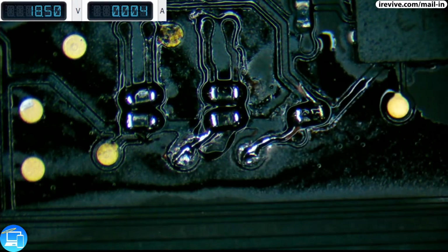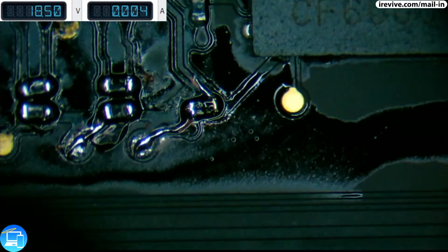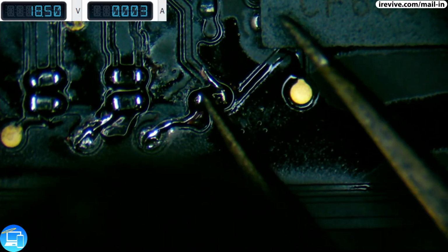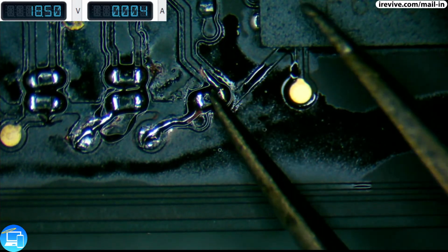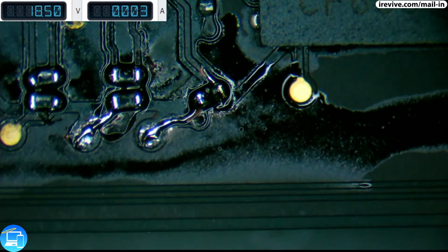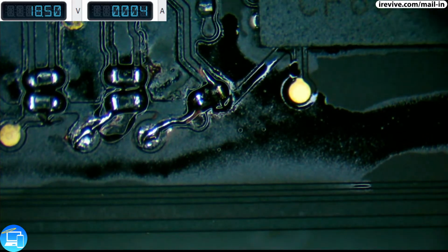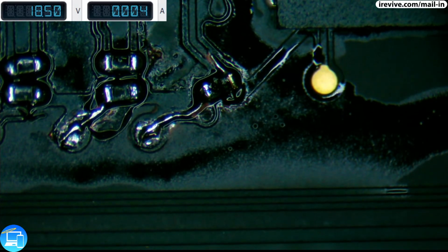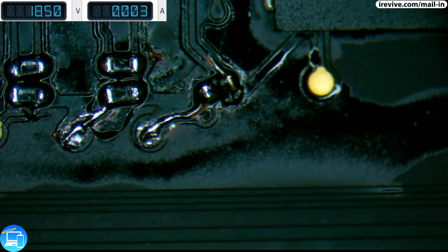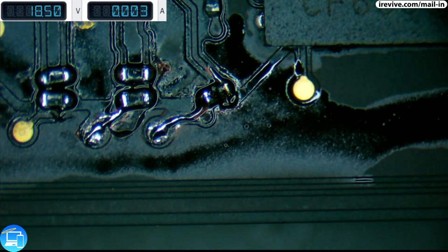Okay, so they're nice and melted. Now what I gotta do, this is gonna be a little tricky with my shaky hand, is touch the right resistor. The one on the right. Okay. And see, it's shifting just a little bit too much. But I think we may actually be fine. It's really hard to see, but I can see the jumper wire underneath, and the jumper wire does appear to be touching the via. Let me see if I can touch it up just a little bit more with some solder.